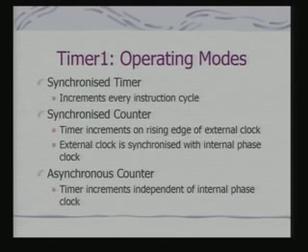It can operate as a synchronized timer, it can operate as a synchronized counter, it can operate as an asynchronous counter. Now there is a basic difference between them, and these differences are interesting. When it works as a synchronized timer, not counter, it increments every instruction cycle.